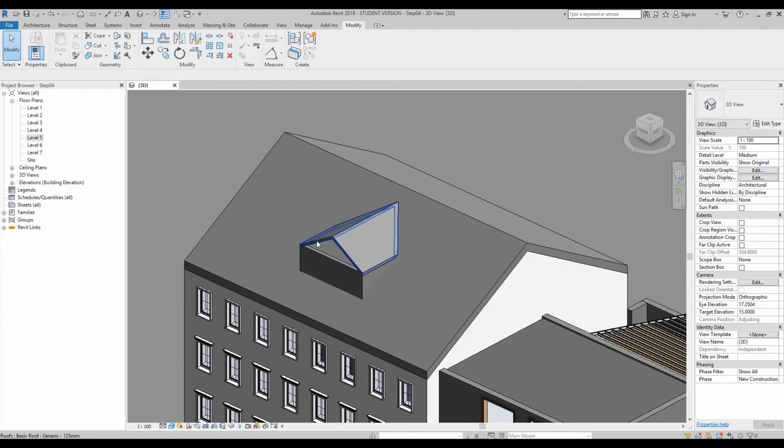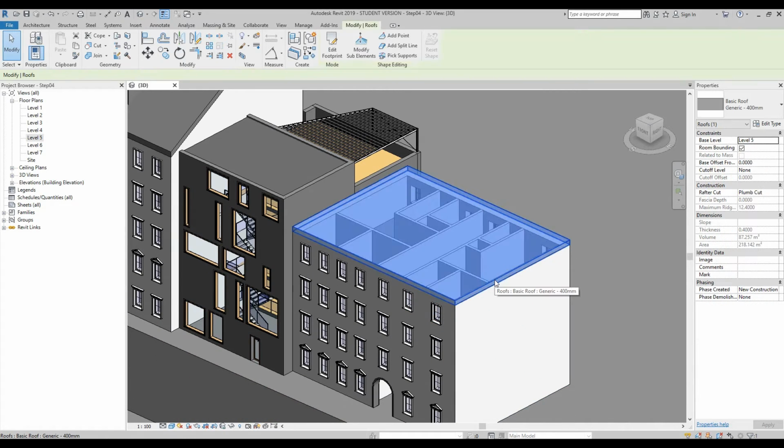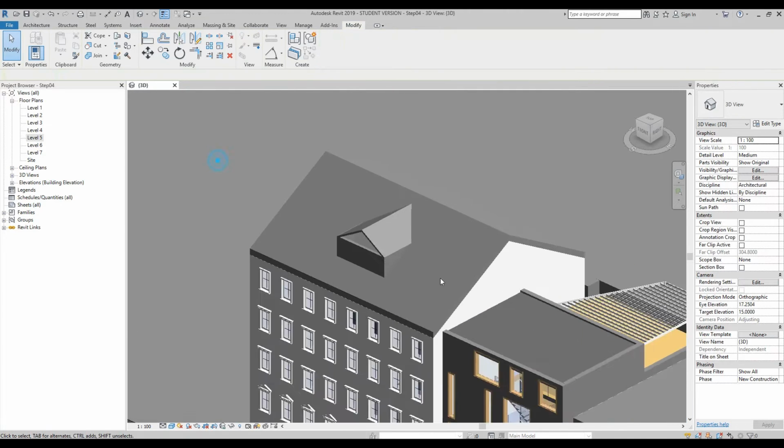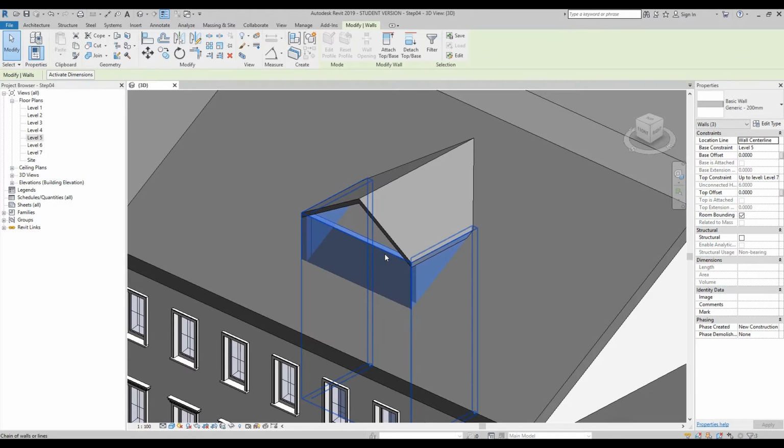Now just like we did over here with these walls, we joined it to this roof, that when we had a pitch the gable ends closed. We're going to do exactly the same with this. So we'll hover over one roof, press tab once so all three are highlighted, click your mouse, and then in the ribbon at the top where the user interface is green, you see two buttons that say attach top base and detach top base.